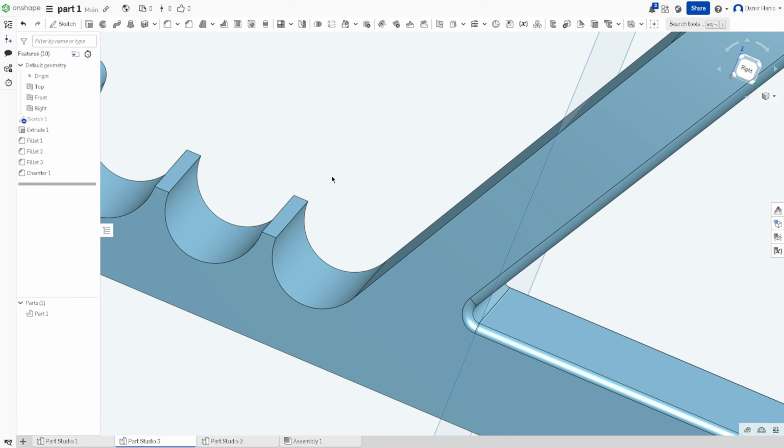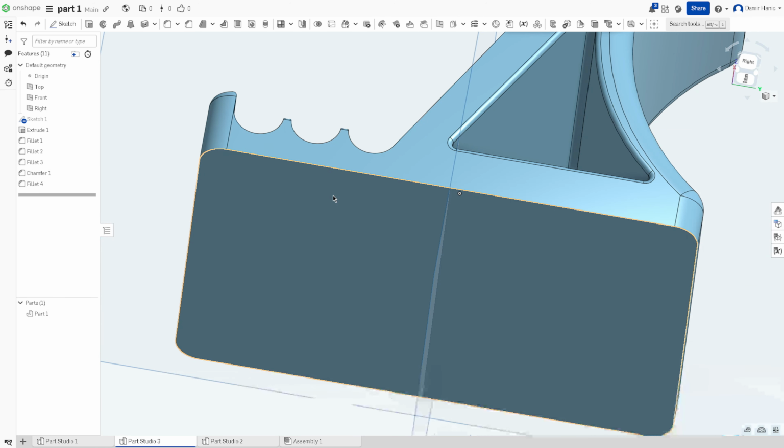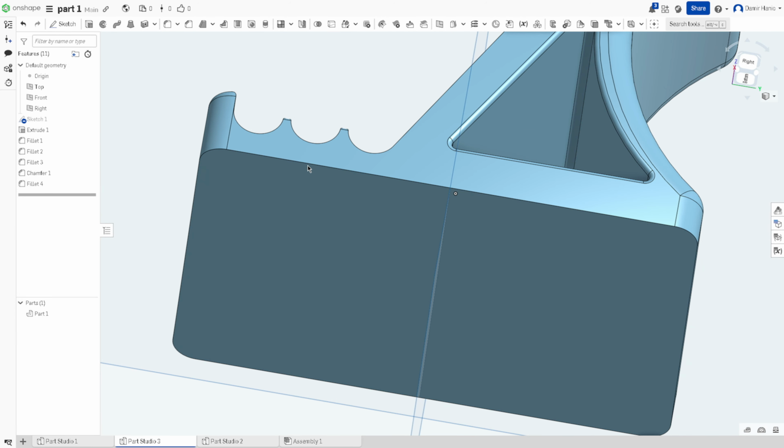And this can potentially damage the phone a little bit. So we're going to go again to fillet, we're going to put 0.05, we're going to add this, and that's it, guys. Why didn't I chamfer these sides? Because if we chamfer or fillet these sides, we're going to have artifacts while printing, which we're going to explain in the next video.